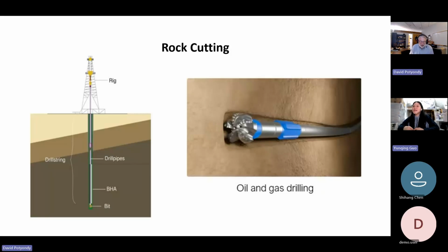So the strength of rock is very sensitive to confinement. When you're cutting, the same thing happens. If you have this weight of the fluid applying confining pressure to the surface, it takes about 10 times more energy to remove the same volume of rock.